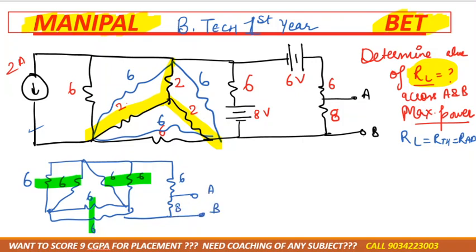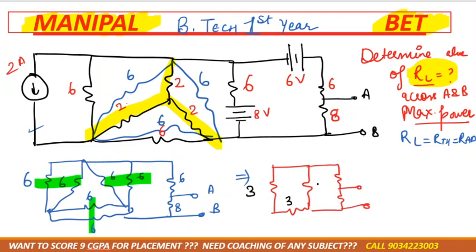Now don't consider 6 and 8 as being in series, they are not in series. After solving the 6 parallel, 6 means 3, then 3 and then 3, right? 6 and again like this, so 3 and 3 are in series, that would be in parallel with 3 plus 3, 6, 6 is in parallel with 3, right? It will become a single circuit.